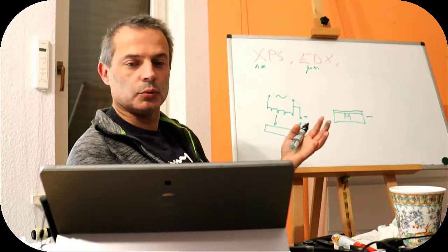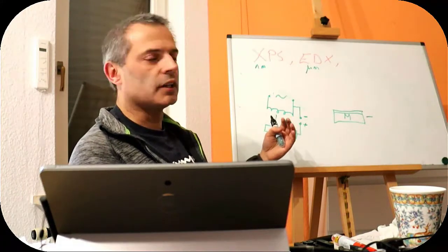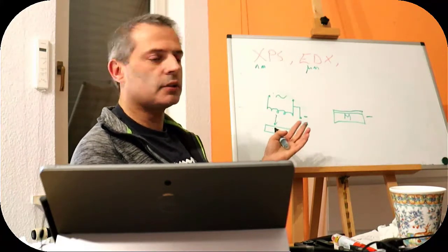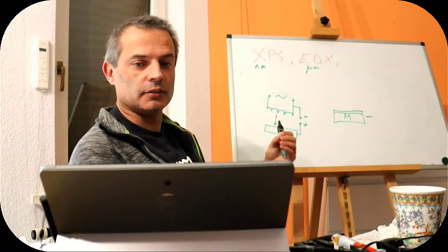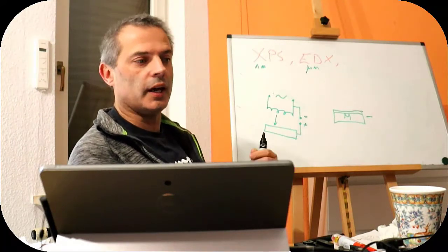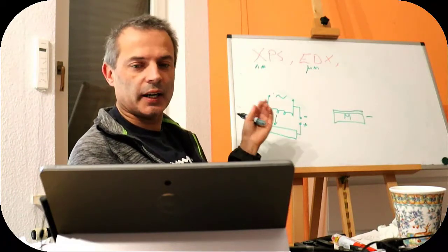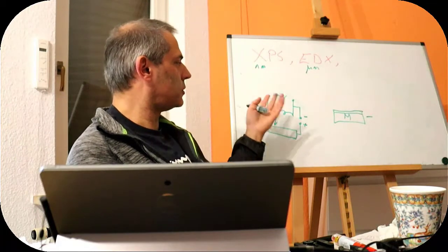Conduction works in a vacuum, but convection does not, and that means that if we put 100 watts of heat into a filament, but we take very little of it out, it will get a lot hotter in a vacuum than it would in the air. That's good and bad, but in this case it's bad because we have to actively cool our anode.